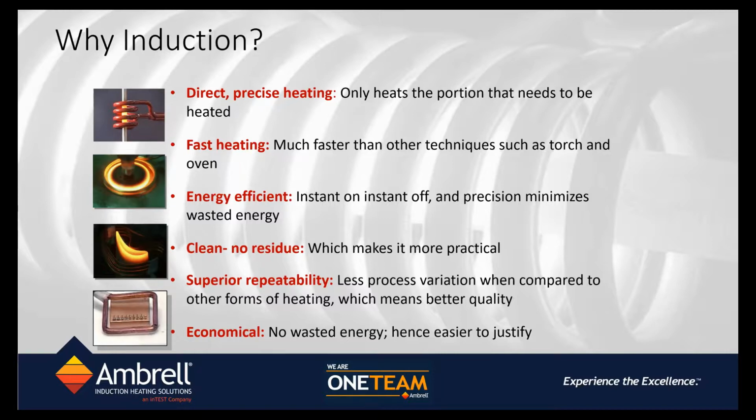So the energy that's required in those kinds of applications is not just the energy that's required in the part, it's the energy of heating the air, it's the energy of heating the fixture, and it's the energy required to heat the entire part, which may not be required.